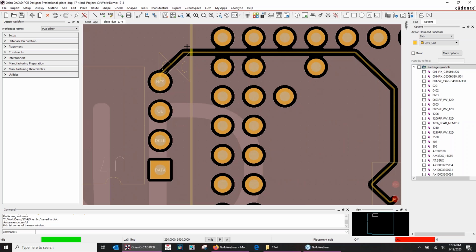It's following the DRC rules. It's giving me that gap because those are the rules I put in the Constraint Manager, which I call the brains of the operation. It's doing all that for me. No matter how I route it, it opens up and allows me to go in there. That's dynamic shape. If this was static shape, I'd be getting a DRC.